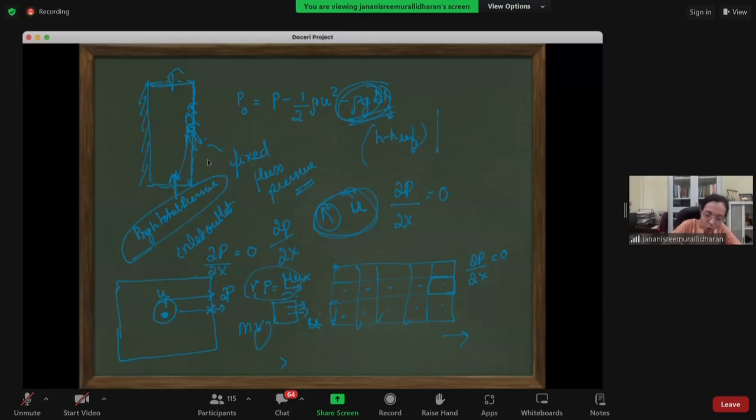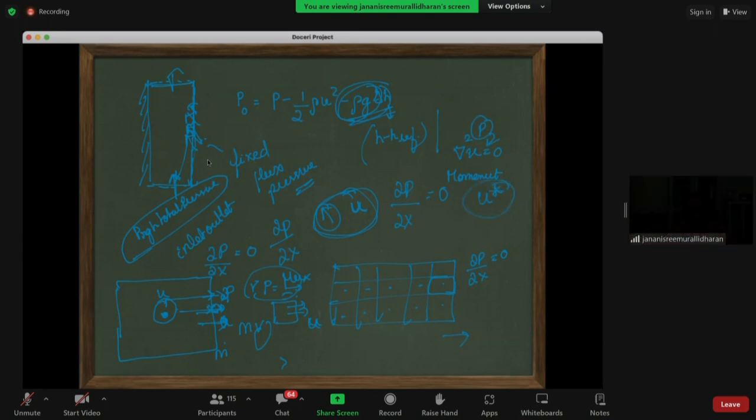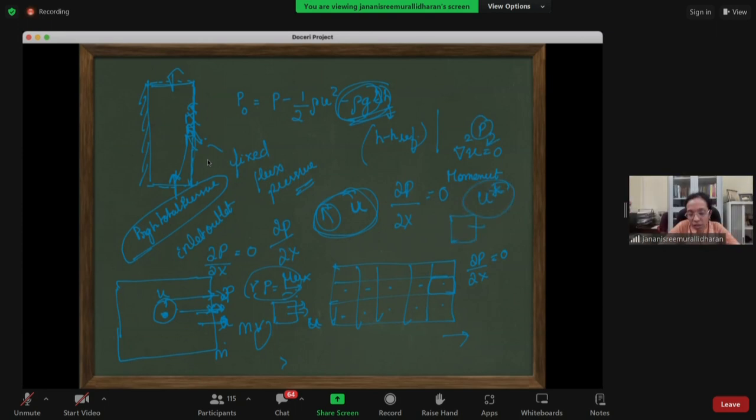So if you are getting a u value here, right? Let me rephrase. If you're getting a flux here, an m dot value here, basis your previous iteration, there is a continuity equation, and then there is the momentum equation, which is going to be rewritten in terms of pressure. Okay, so when you're having the momentum equation and you get a U star value, with the intermediate U star value, you will calculate the mass fluxes in every part of the cell.